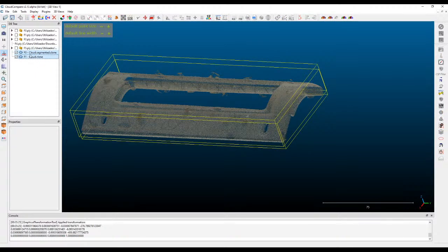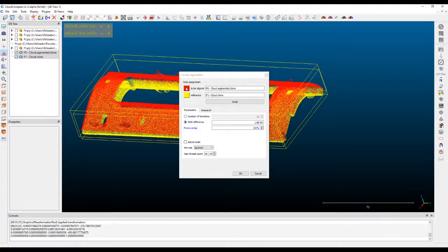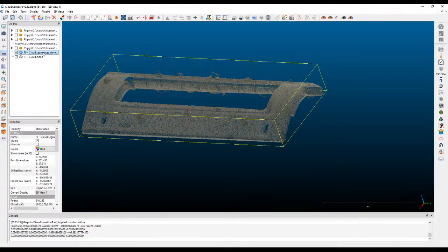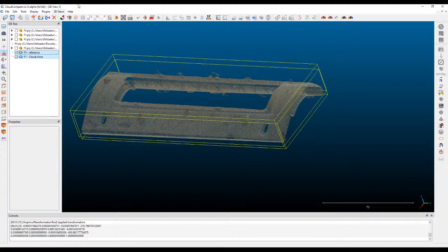Okay, so we'll select the tool and we'll select fine registration. Here you have to define which is the face that will be stable. If you remember, we aligned the faces to the top. Ideally you align one that is where you want it and you use that as a reference. One of the good practices is to just rename the face. So you double click it and you name it reference, and the others can be whatever name they are.